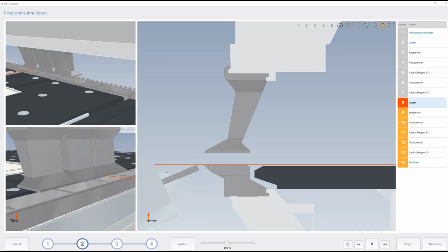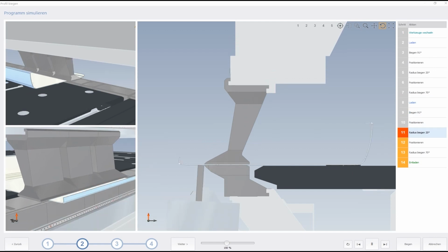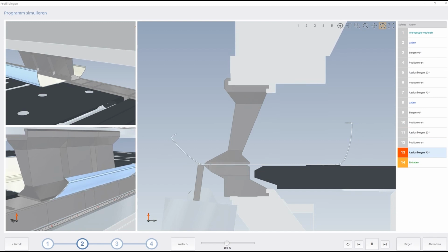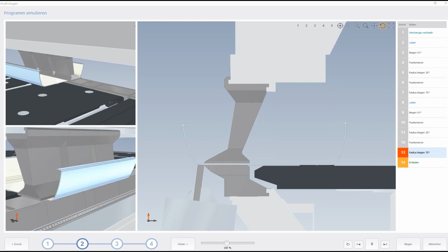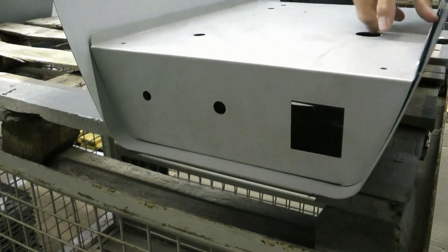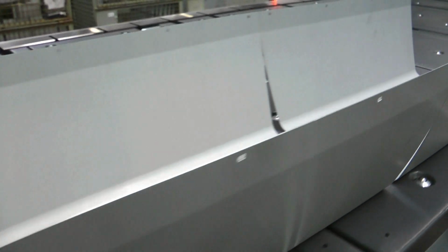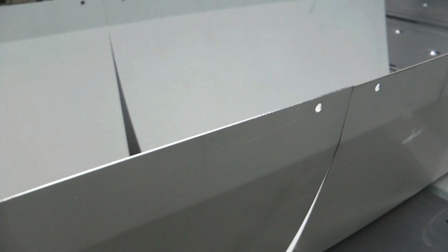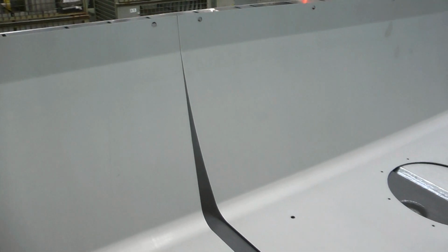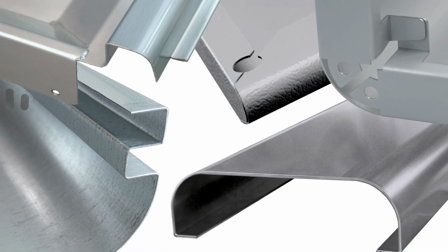The software calculates the required number of bending steps, the step length, and the angular position of the folding beam for each radius. Material-related influences on springback are also considered by the software. This procedure guarantees exact bending radii that speed up the assembly of components and leaves nothing to be desired in terms of repeatability. Folding technology with radii. Flexibility without effort.